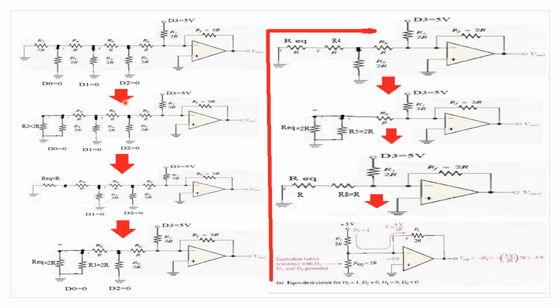In next step, we can simplify the circuit by considering this portion. Here we can see that this resistor is grounded and also this resistor is grounded. So these two resistors are grounded. Here we can see that these two resistors have one common terminal and the second terminal is also common, hence it is grounded. So we can replace this section by a parallel circuit like this.